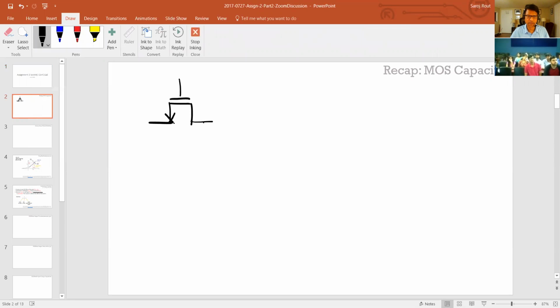And we're following this notation here. And as I said, again to repeat, the source and drain are really symmetric. It's how you bias it. So once I show it as a source, that means it's at a lower potential than the drain for NMOS, and for PMOS it's the opposite. And usually the bulk is shown as another terminal here.